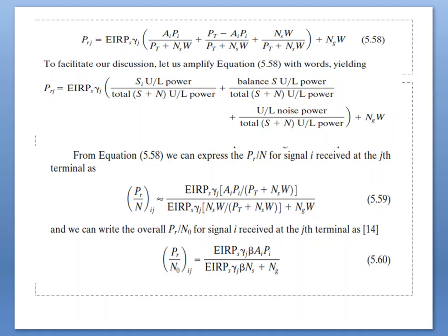The users must cooperate with one another, not exceeding the agreed uplink and downlink transmission power limits. The above equation states that the portion of downlink EIRP dedicated to any one user is determined by the ratio of the user's uplink power to the total uplink signals plus noise power.